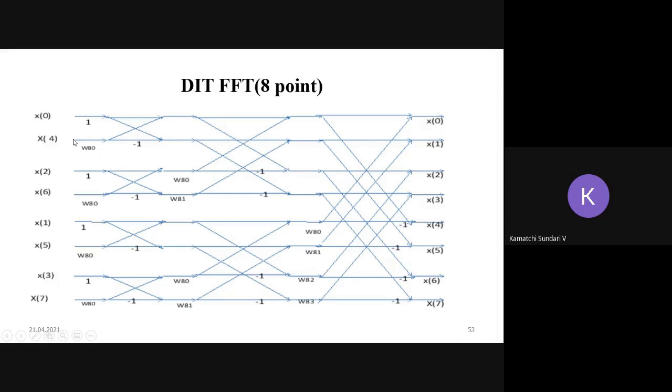And also we have to give our twiddle factors at the input side of each stage. Here N is equal to 8. So W8 power 0 is the twiddle factor, W8 power 0 in the alternate lines: the second, fourth, sixth and eighth lines.